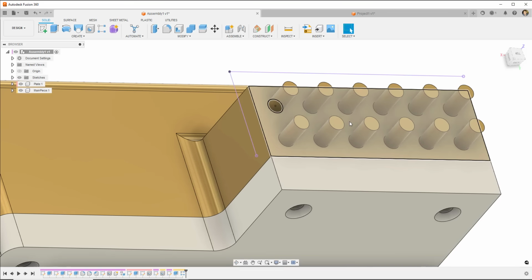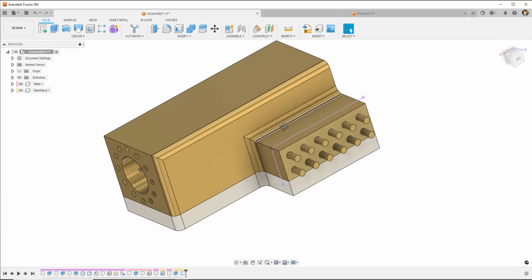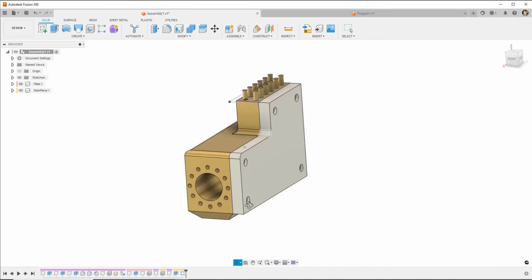Now, which is the best way? Well, it really depends how complex the object is that you're extruding, and how many there are. We did have to go through and select every sketch object to extrude it, which automatically should tell you it's a long way around. So really, it's probably best to do your sketch, extrude that single item, and then do the pattern of the objects. And that way, you're only selecting that extrude once, and you're patterning that. But sometimes it might be better done the other way. It depends on the process. So anyway, I don't know what this object is going to be, but we've gone through some commands here.